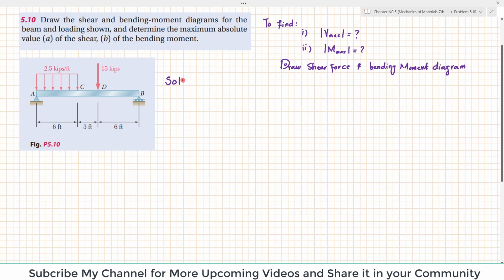The first step is to determine the reaction forces at points A and B. For that, if I remove this support A, there will be a reaction force RA, and if you remove this roller support at point B, there will be a reaction force at point B. First, I apply the equilibrium condition: the sum of all moments about point B is equal to 0, taking counterclockwise moment as positive.